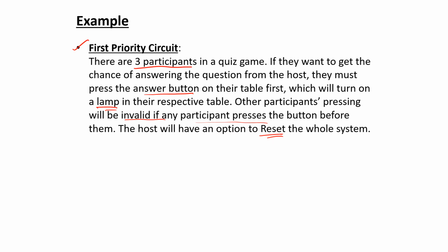So according to the description, if we consider the input devices, we can say that 4 push buttons would be necessary. One of the push buttons should be for the host in order to reset the entire system, and 3 other push buttons for the 3 participants.